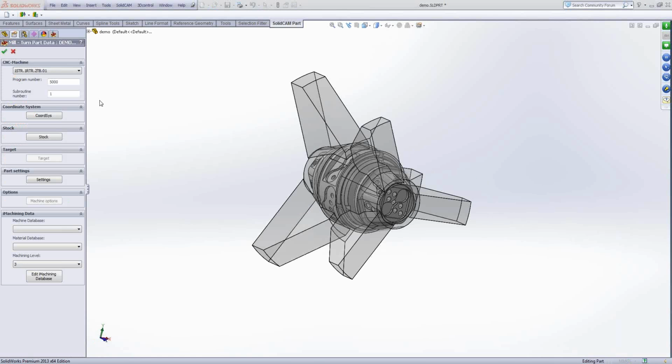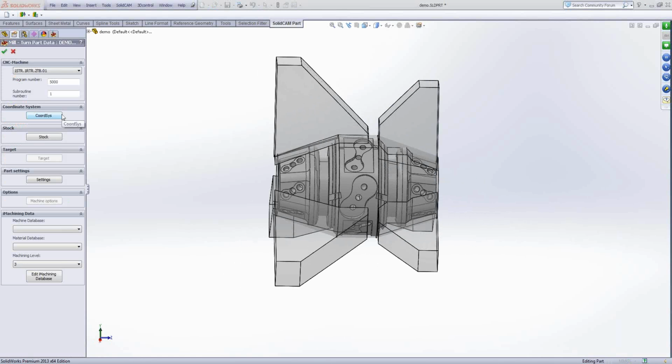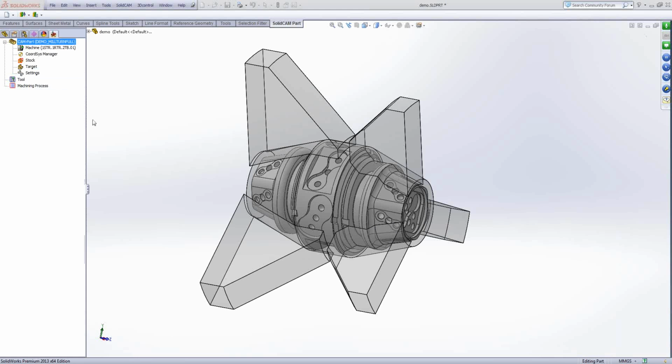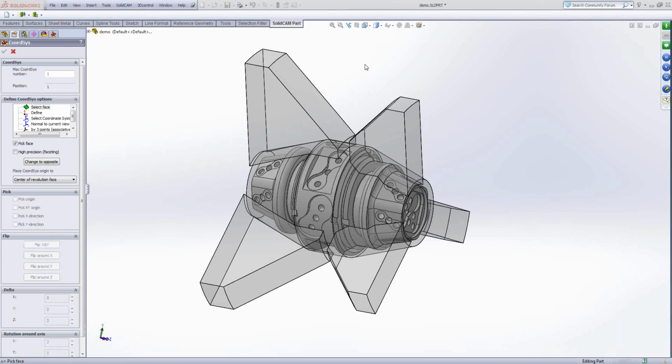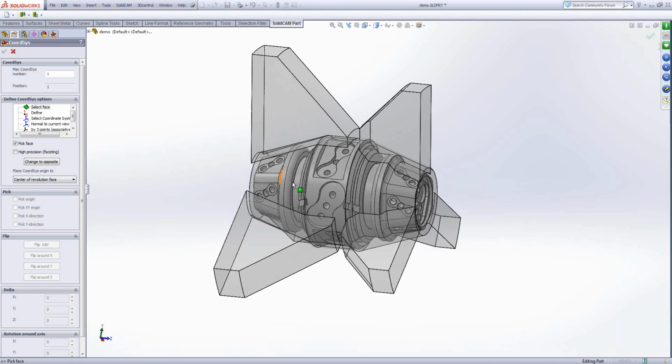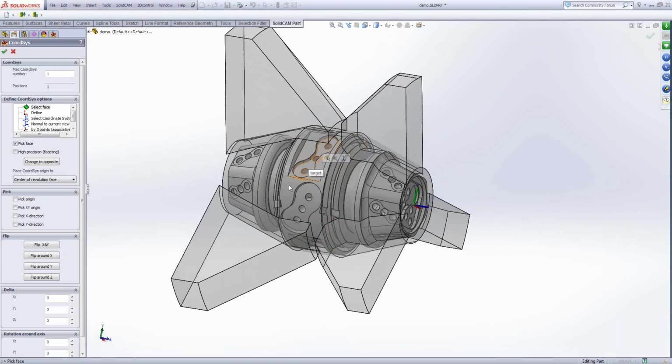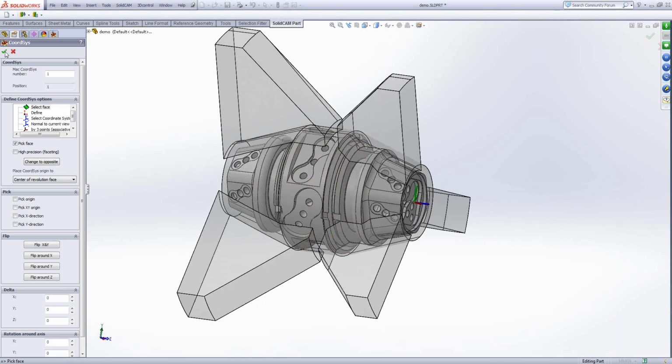And the first thing that we need to do in SolidCAM is coordinate system, home definition. I select a machine, 2 tables, and an upper turret with B-axis and a lower turret with a type rotary. Mill turn, we define home as center of revolution phase, and I will touch the biggest diameter on the part, and I show you why.